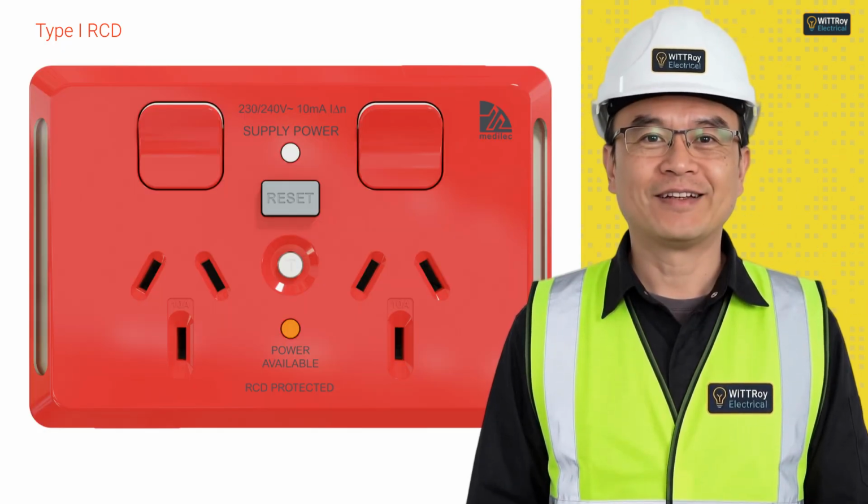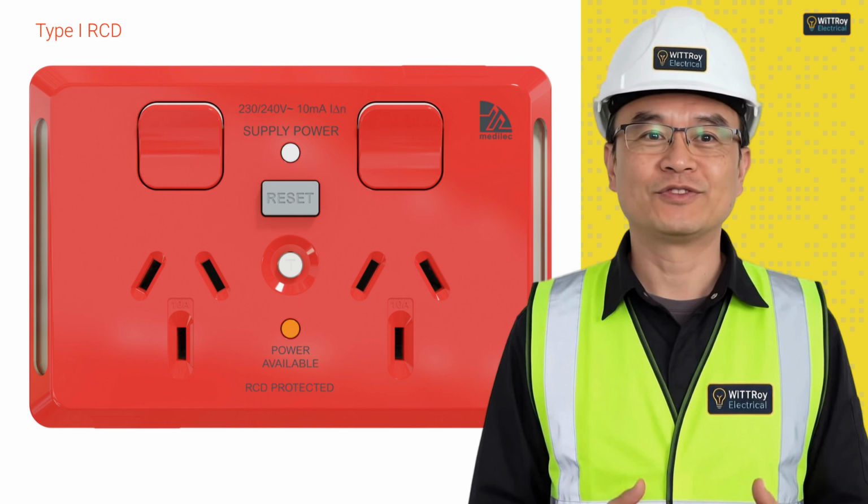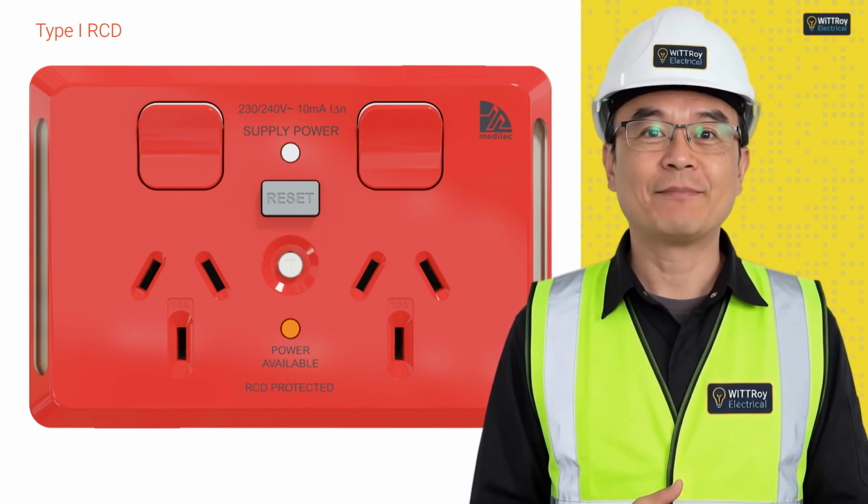Let's look at this device. This is a Medilec RCD protected socket outlet. The product information says it uses a Type 1 RCD. I can see 10 mA on the label. That means it trips at 10 milliamps earth leakage.